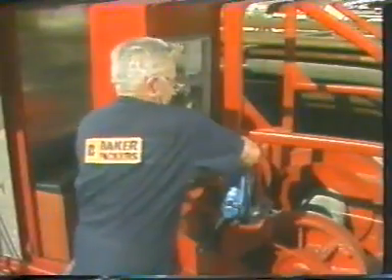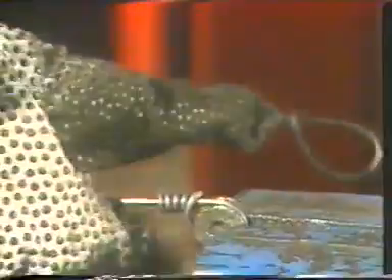Let's look at the components of a typical tool string individually. The wireline socket provides the means to attach the tool string to the wireline. There are two basic types of wireline sockets. The first type requires the wireline specialist to tie a wireline knot to attach the wire. The knot is tied by looping the wire around the disc and wrapping the wire back over itself to form the knot. This type of socket is normally used on carbon steel lines with diameters of 0.092 inches and less.